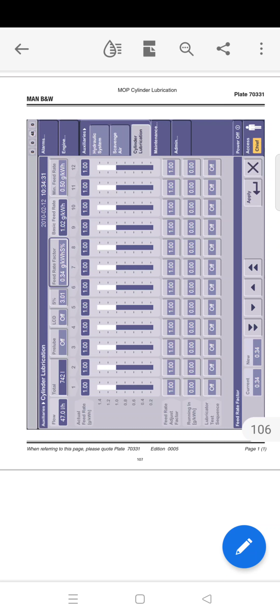If you press this button on, it triggers a pre-lubrication on all cylinders and evaluates feedback from the lubricators. By default, each lubricator is activated 20 times at the fastest possible speed. Pre-lubrication can only be activated if the hydraulic pressure is present. So guys, your electrically driven servo oil pump should be running in this condition. This demands that the engine is put in the state standby or that the hydraulic starter pumps are set to manual operation.